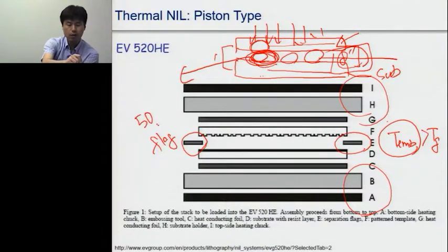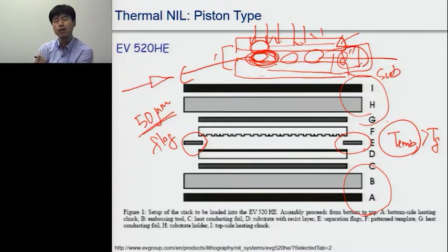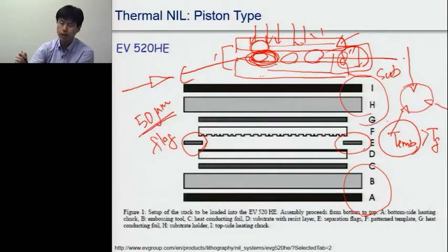which are about 50 micrometers thick, a triangular shape of very thin metal film. From the top, whether it is a 4-inch or 8-inch wafer, those flags are inserted first and physically separate the master mold and the substrate, and then we increase the heat over the embossing temperature.